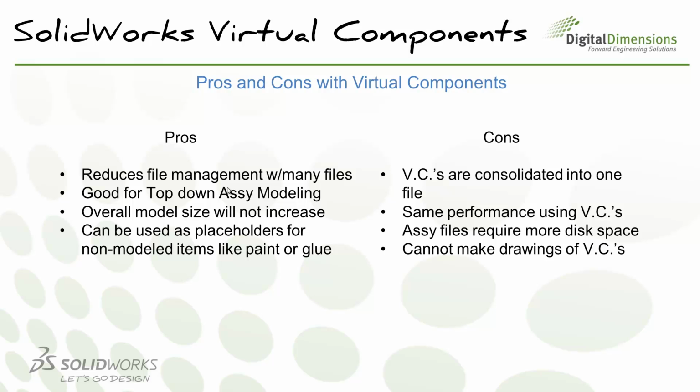Now another con, I guess I can put it into the con section, is this is actually a common question I get. If I go in and I create components as virtual components, will I still see the same performance? Will I see actually a faster performance with regards to rebuilds, because it doesn't have to go in and find all these references? And after some research, I don't see a change in performance with regards to SOLIDWORKS when you're working with regular components versus virtual components.